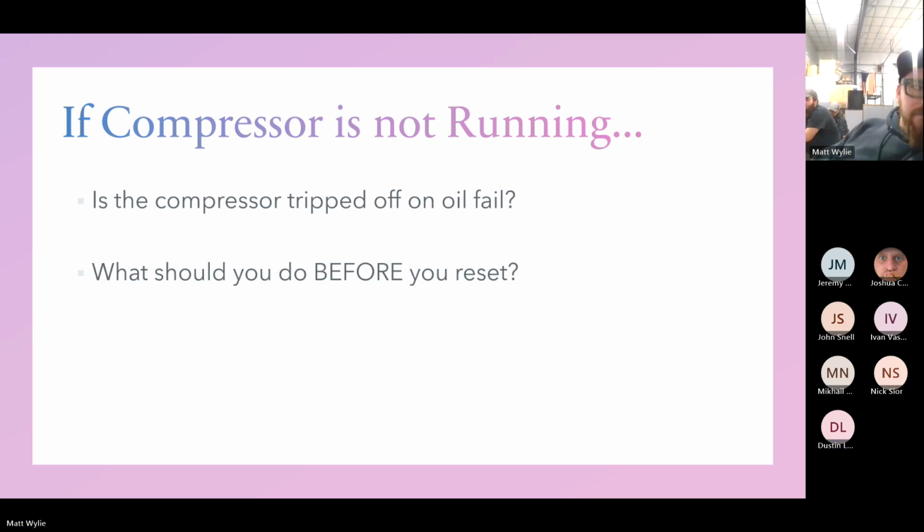That everything electrically checks out. What are some common causes of an oil fail? Dirty oil. What else? Yep. And that screen inside the pickup will plug and cause a false fail even if there is oil. What else? Low refrigerant. Okay. Usually, if you're low on refrigerant, you also have a chance of being low on oil too, huh? Mhm. So what else?